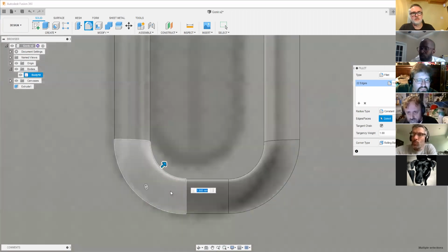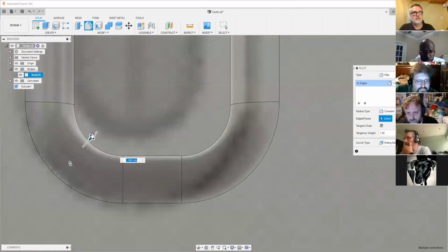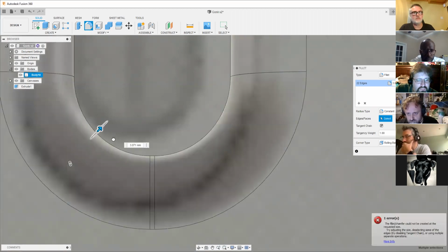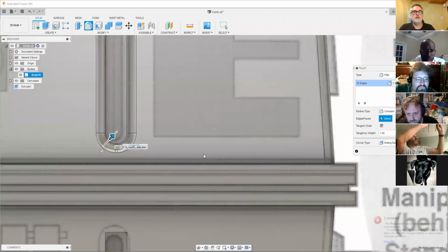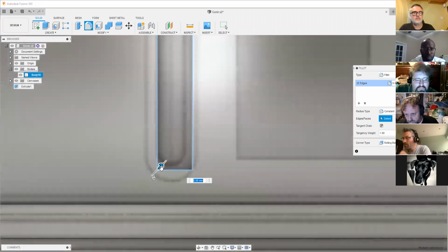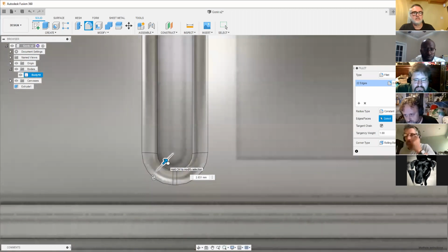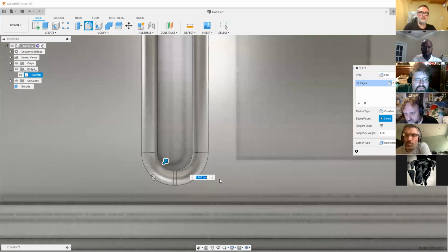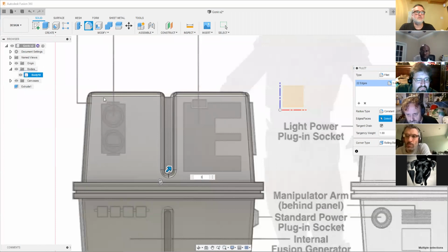And the limits are, if you look here, you can fillet with this flat piece in the middle. You can fillet it, continue, and then once those two touch, it goes beyond the capability of the fillet tool. So fillet's very useful, but it has some limits when you go beyond the dimensions of the actual model that you've created. So I'm going to drag it in and say I'll get away with maybe, let's try 3. I'll try typing 3. So I've got 3, which gives me a nice round fillet. The reason I'm typing 3 in as opposed to dragging it is I want to replicate that same fillet on the bottom, so I'll get evenness. So I'll click OK on that.